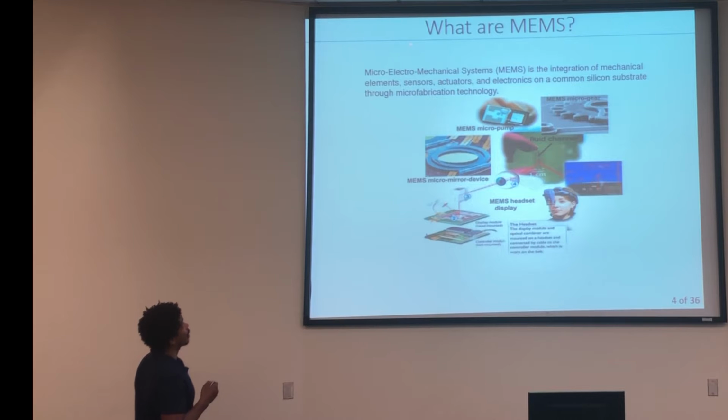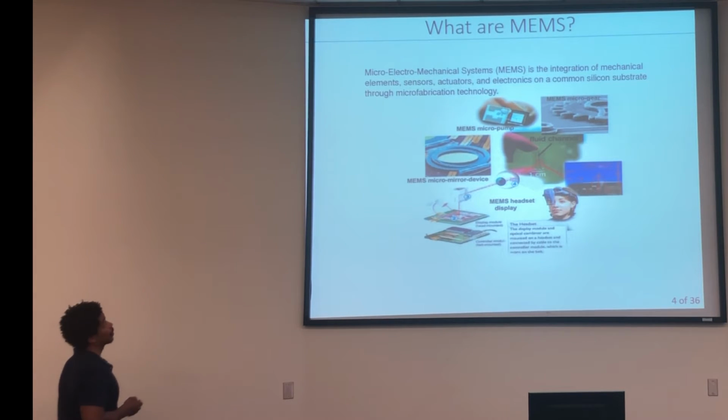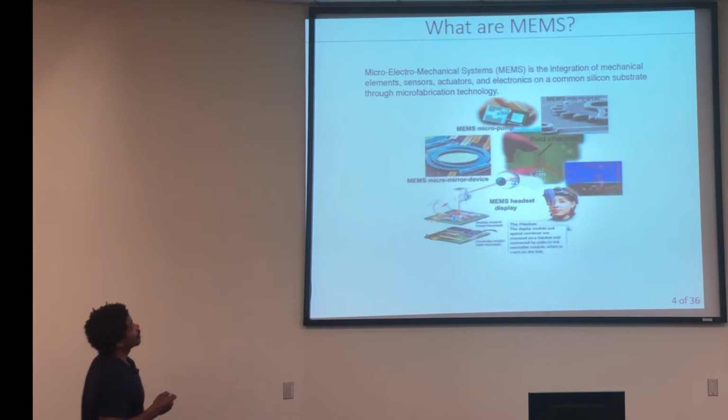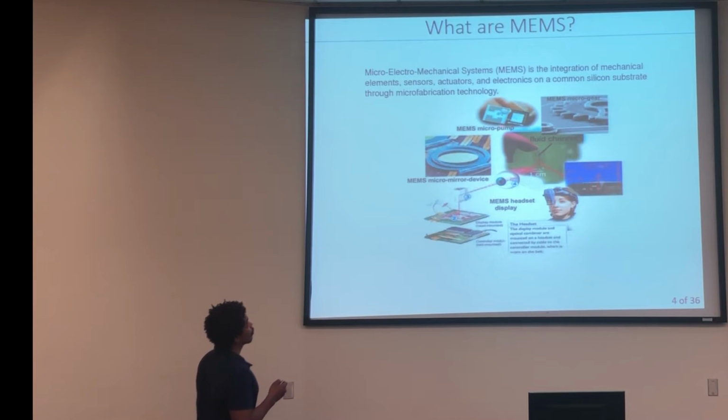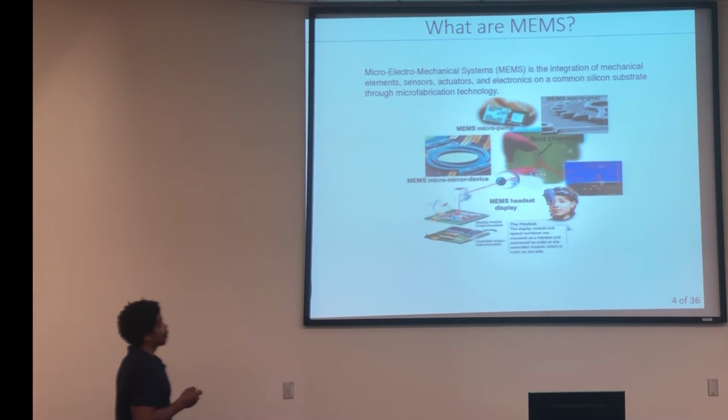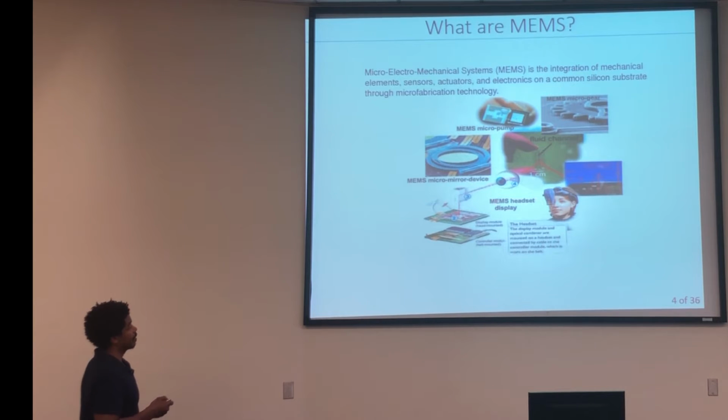So it's the integration of mechanical elements, sensors, actuators, and electronics on a common silicon substrate through microfabrication technology. Here are some examples, like a MEMS micro pump, a micro gear, a micro mirror device, a headset display, and a fluidic channel where you can do some mixing and things like that.